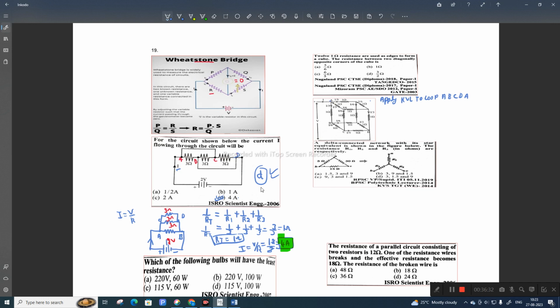So I by 3, I by 3, I by 3. Right? Then further the current is going and has again two branches to divide. So I by 3 divided by 2 becomes I by 3 times 1 by 2, so you will have I by 6. So that is what we have here, I by 6. I hope the concept is getting clear for you.